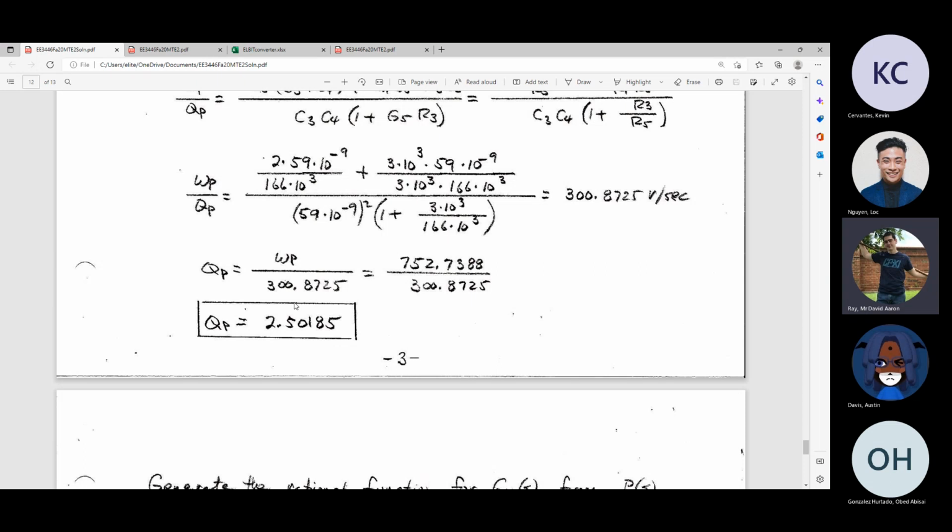That means it's a really quick response, but it overshoots what I want. If I want 48 volts, whenever I turn on that device, it's going to give me like 70 volts. And then it's going to try to stabilize back down, and maybe it'll keep oscillating around 48 volts. That's what happens whenever you have a very low quality factor.